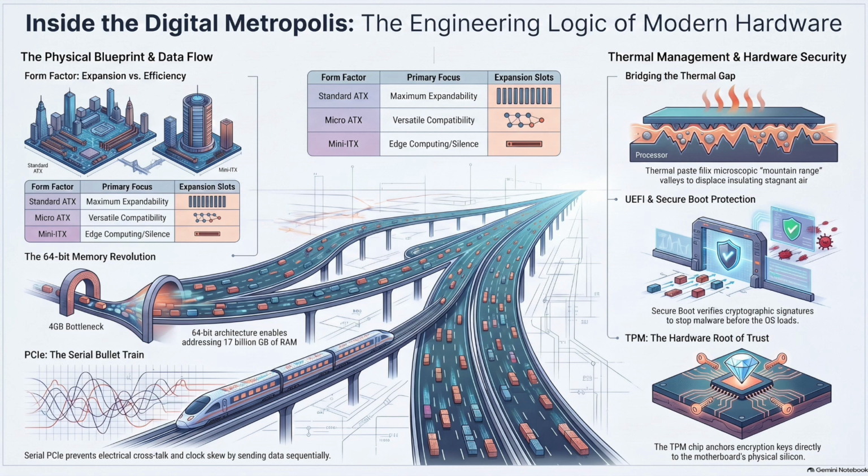Oh, I see. Gamers and video editors often engage in overclocking. They manually increase the clock multiplier and electrical voltage of the CPU to force it to run faster than the manufacturer's specifications. Pushing the chip beyond its stated limits. Yes. And when you increase voltage, heat generation scales exponentially, not linearly. A massive copper heatsink simply cannot pull the heat away fast enough at that point. So the liquid system acts like a car radiator. It's the exact same principle.